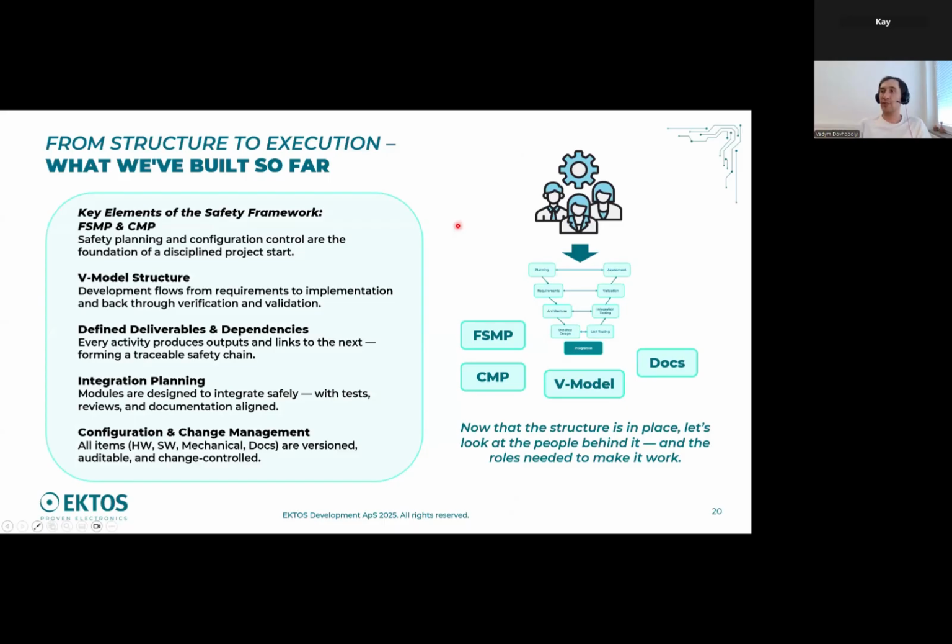Yeah, and just to summarize what we looked at here: we are starting from the functional safety management plan, the configuration management plan, and developing process documents during execution. So we are suggesting this strategy. Run the product through the V-model, which is described in the functional safety management plan. Put all documents in place, create a map of connections between documents, and understand the sequence, the roadmap of your product, in the configuration management plan, and make the product real.